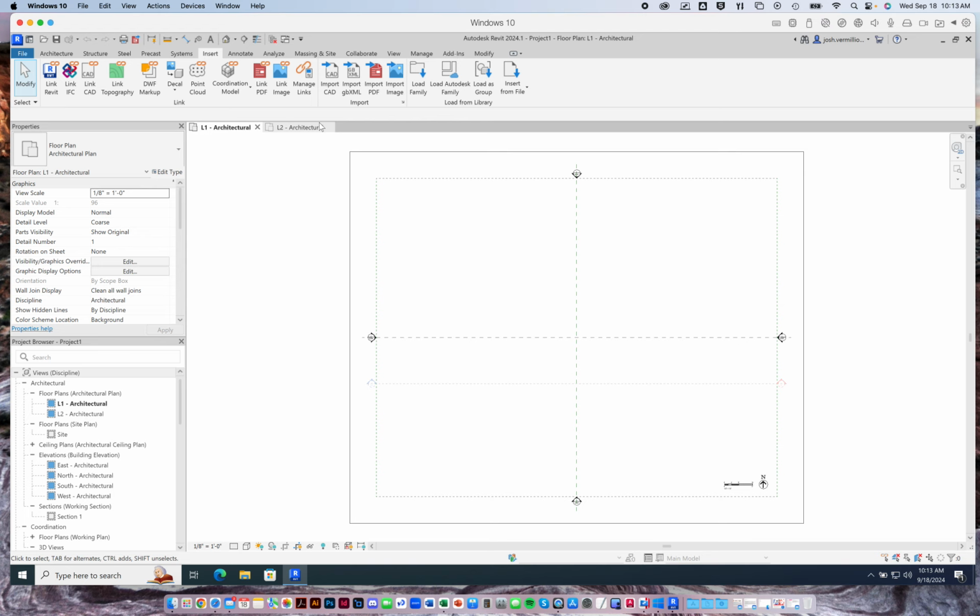What's the difference? Linking will just say, well, I've linked up to this Rhino file. Whenever I open up this file in Revit, I'm just going to refer back to the Rhino file, however it is, and import it in temporarily, right? So if I go back into Rhino and change the file around, when I open up the Revit file, the link file will have been updated, right? And I'll see the updates. If I import it in, then I'm just importing the geometry from Rhino, making it into Revit. And I'm just going to go ahead and do that first, right? I'm just going to say import CAD.